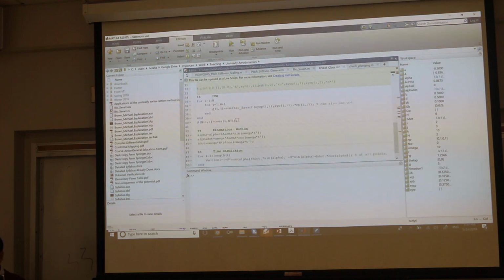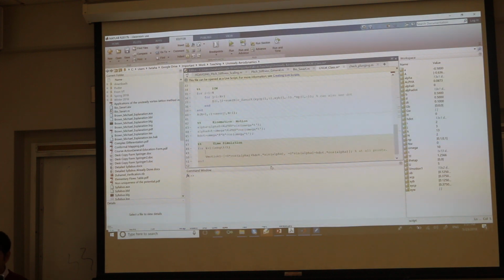Okay. Influence coefficient, your alphas and stuff. Let's go here. So the time simulation, what is the heart of the time simulation? What's the thing that we really must do every time step? Update the wake vortex, like add it up. Yeah, no, this is to make things work. What's the heart of it? What's the essential equation that you solve each time step?